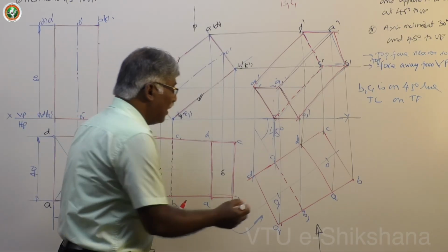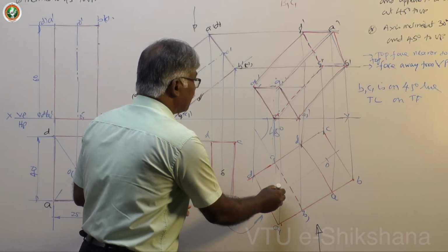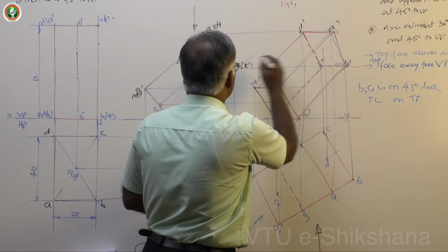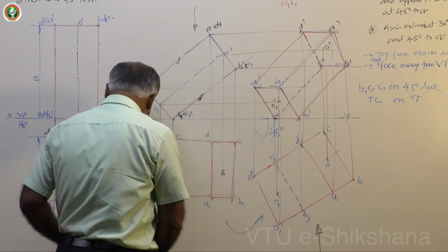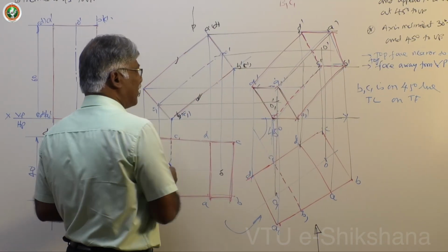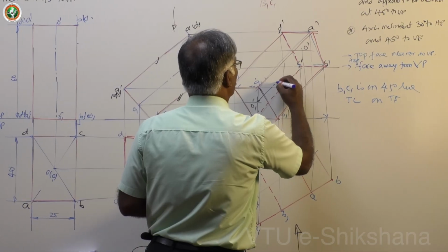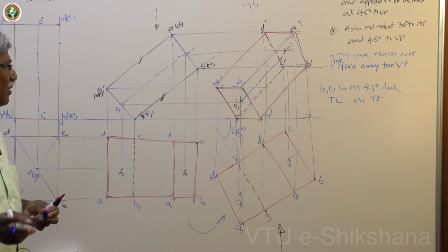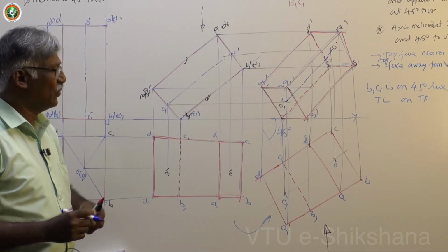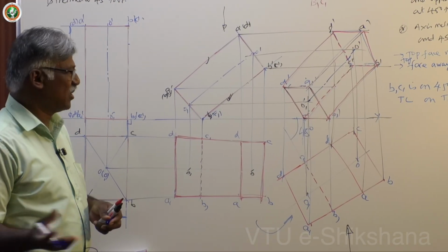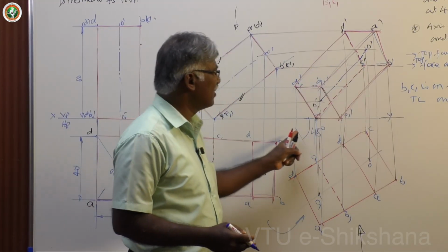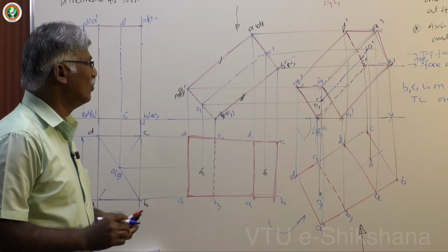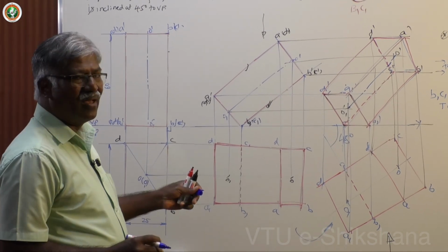Now, identify the axis. This is O1 dash, this is O dash. That's all. Now, join them with the particular convention, full line hyphen, full line hyphen. Okay, that is the axis convention with 0.25 or 35 in computer. Here, medium line. We use H pencil, 2H and HB. HB for all the visible lines in the drawing sheet. Even in casual work you can do, and the sketchbook also you can use. So this is the method you complete.